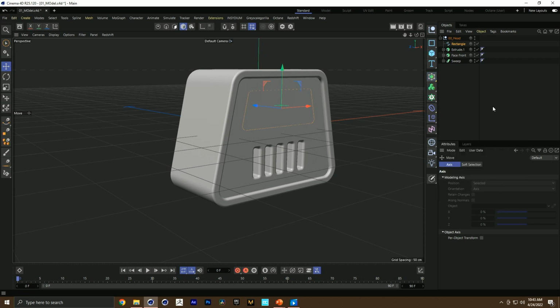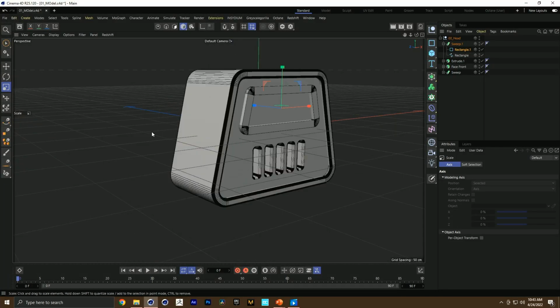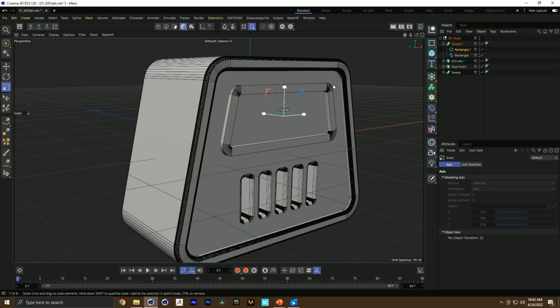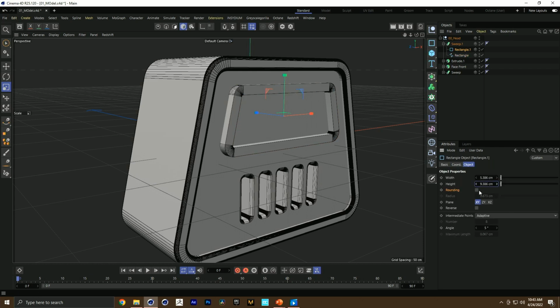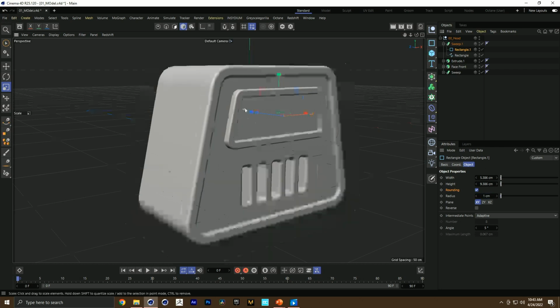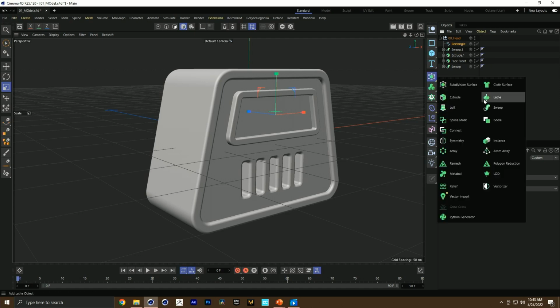So drag, put that in a sweep, holding Alt, holding Shift, put another rectangle, just making a little border for this eye. And then let's get a little deeper, add some rounding to it. Good. And then make a copy of that, pull it out, and put that in an extrude.